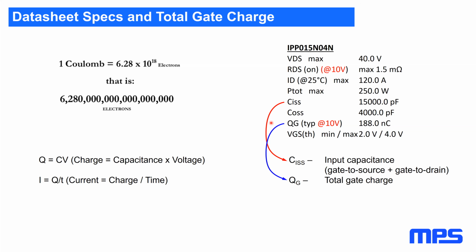So quite often you'll stick a resistor 10 or 20K from gate to source, and that's all that does. Think of power up, for example: maybe the power supply turns on and it takes the gate driver a few milliseconds to wake up and actually drive the gate. That's why that's there. You do have to be careful though with high side MOSFETs. A lot of gate driver ICs and bootstrap circuits, for example, can't drive much current. So you do have to be careful not to cause too much leakage on a high side gate.